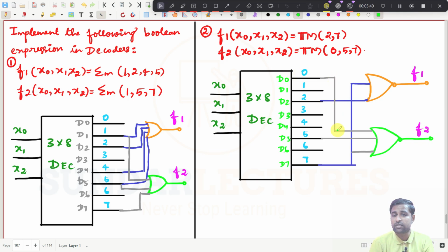So this 1 is actually connected to this NOR gate. If you are getting a 1 to this NOR gate, then what happens here? Can you understand? If you get any 1 here, then this output should become what now? It will be 0. So F2 is getting 0. So that is what we have given here. So for 0 0 0, this F2 should get 0.